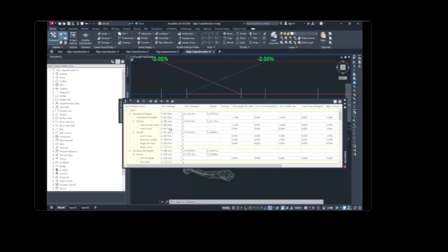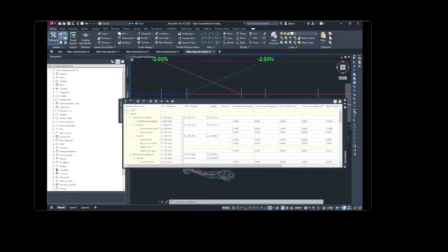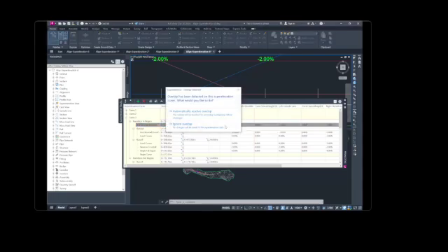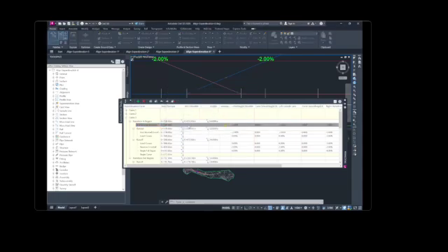In the overlap column, 2 rows display this icon, which indicates that the super elevation stations of 2 or more critical stations overlap. In this case, the station value for the last critical station of curve 2 is greater than the station value for the first critical station of curve 3. Under curve 3, under transitioning region, select the end normal shoulder row. Then click the warning symbol in the overlap column.